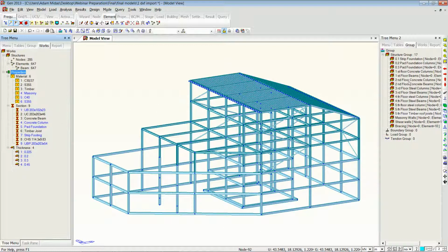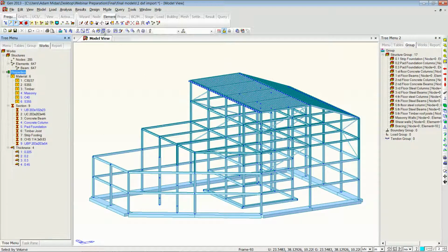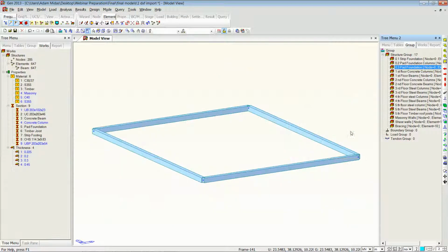So now we're just going to focus on the strip footing. So we just double click, make sure we've got the strip footing selected, and we just take that into working space. Now I just want to select the pad footings at the base, and we just drag and drop them. We can use different isolation functions as well, so I just want to make sure that the mat footing underneath the shear walls and also the stairwell is a 450mm thick footing.